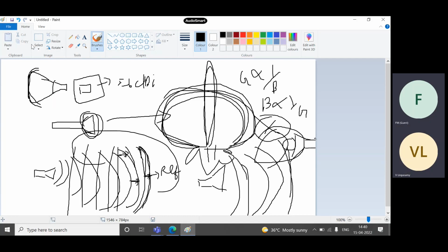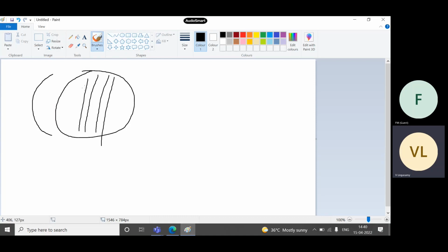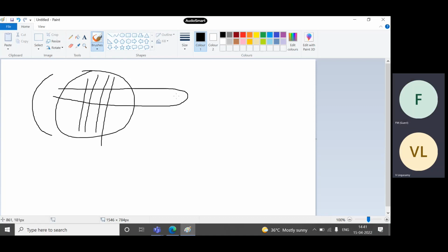Okay, coming back to this. If you want to achieve planar waves very near, the parabolic reflector is used for two purposes. One is achieving the planar waves in a shorter distance, in near field terms instead of far field terms. The other one is that if you are correcting the phase, indirectly you are focusing the beam in a particular direction, so high gain is being achieved. It is a similar concept.